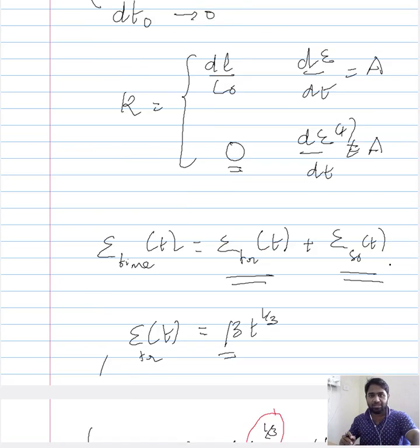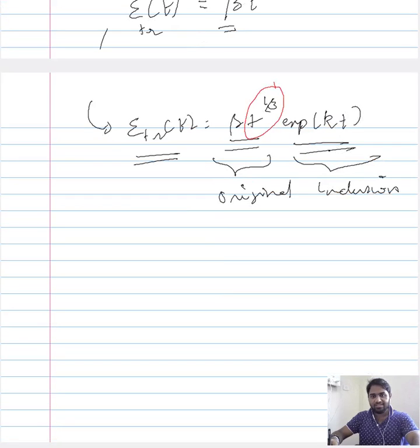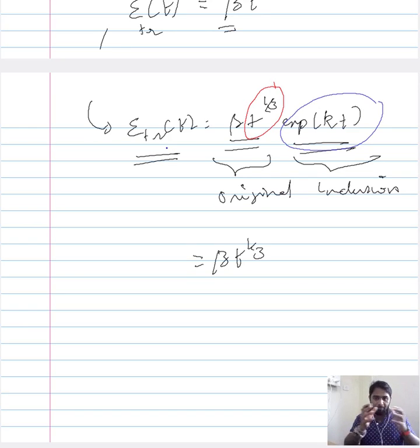However, when you consider this description of the constant K, which shows that this is 0 when the strain rate is not constant, and since in the transient creep region the strain rate is not constant, it ultimately leads back to the original description. The reason we would like to include this here is to indicate that even though this is separately treated, this forms a part of the initial stage of the creep behavior, or stage 1.